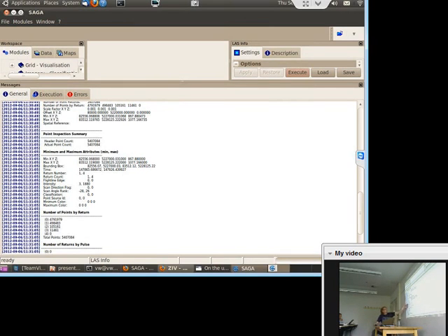Okay, so we see from the attributes which attributes are actually available. We see we have return numbers 1 to 4. We have intensity values from 3 to 1880. We have no scan direction flag, but we would have a scan angle rank, and so on. And this allows us to decide which attributes we actually import from this file. Because if you would select, for example, the flight line edge, we would get zeros for each point. So this is nonsense, and we can decide which attributes are useful for us.